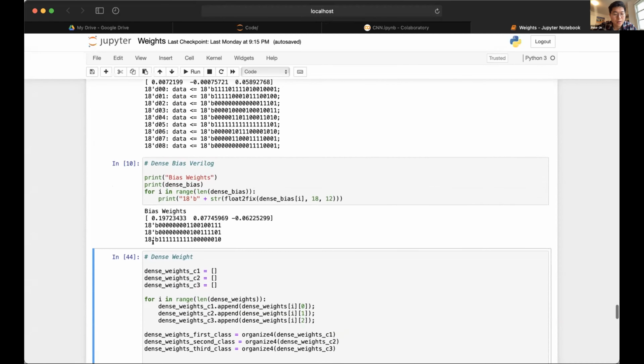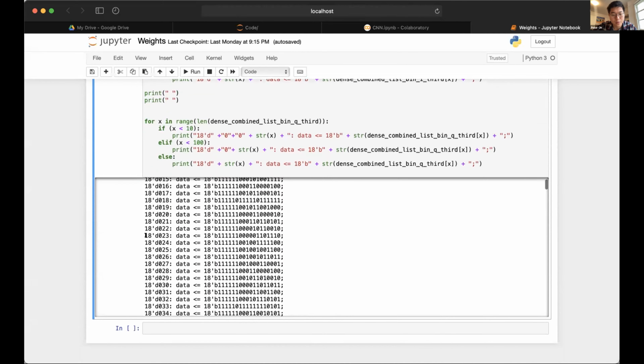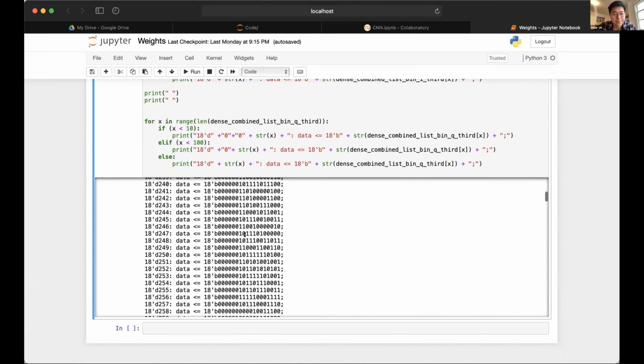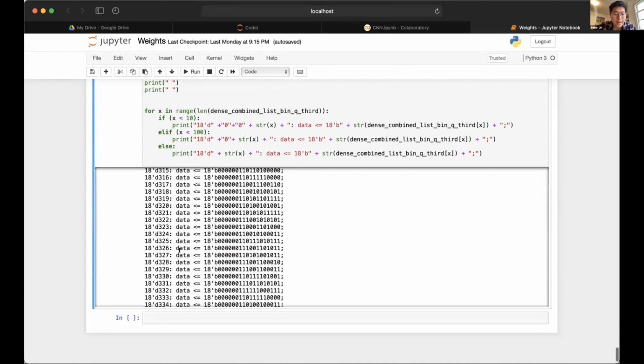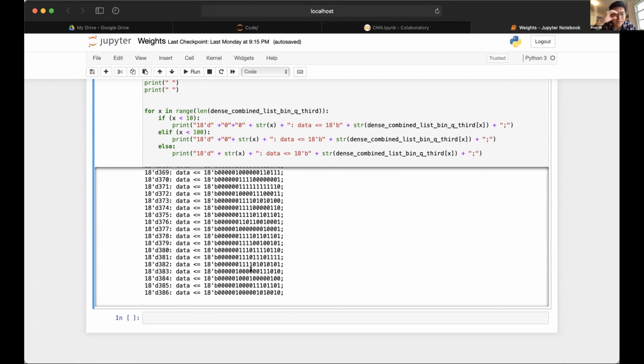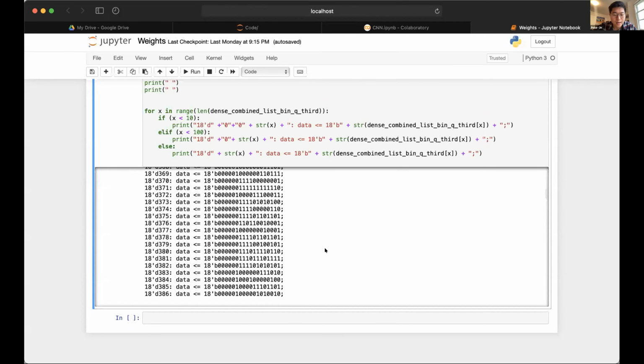And then we did similar things for the rest. The dense weights were where we had the most weights, around 2,325 weights. We had to format them in a ROM table because the other options were maybe reading through the SDRAM or creating a state machine to read through the different data. But we realized that with the ROM table, it would only take a single cycle to determine what exactly the weights were.